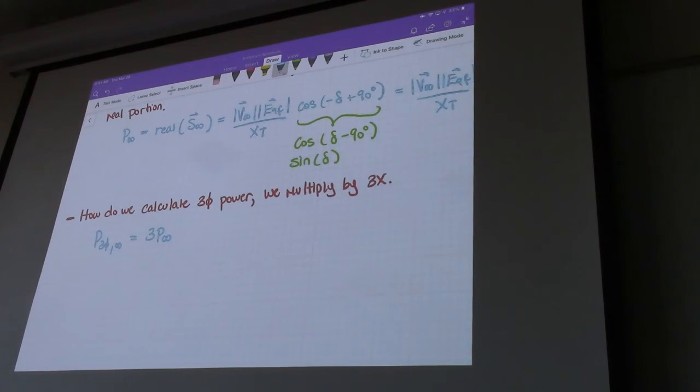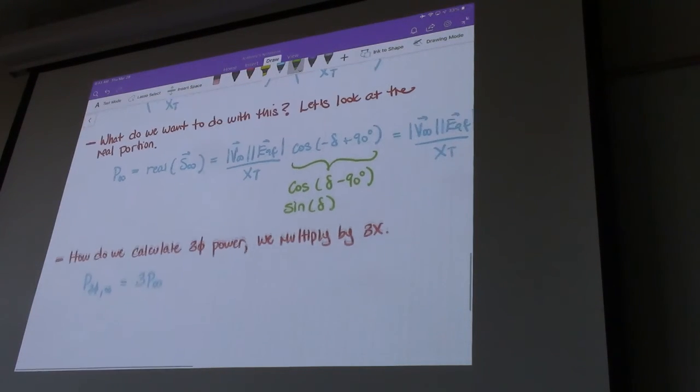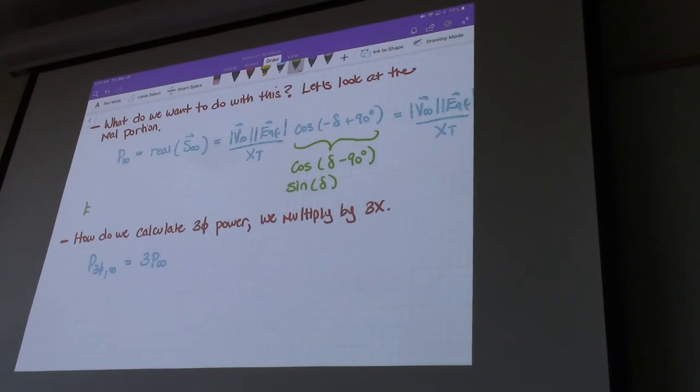Okay, so now let's plug in a couple of values or remind ourselves of some things that we had defined before. So if you remember, going all the way back to the first section of this, the magnitude of EAF is equal to KF, which again, these constants, they're not going to be defined into a literal problem, because they are dependent on the parameters of the machine, times BF maximum, the maximum flux density, and this is going to in turn be proportional to the field winding current, right?